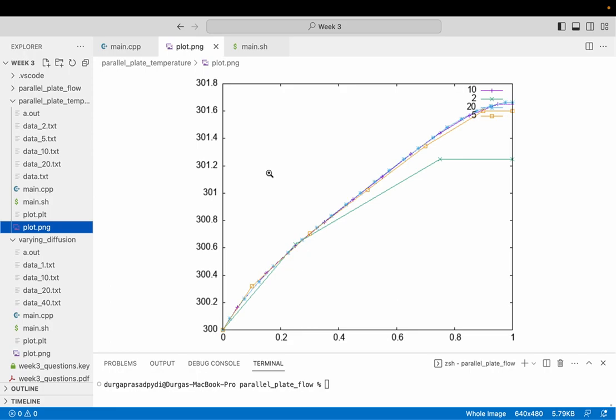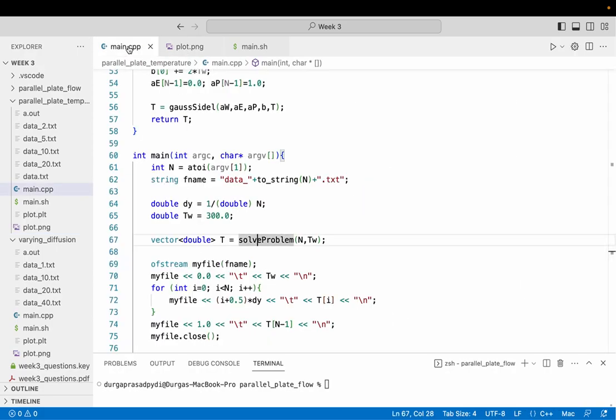Usually this term gets significant only when you have very high speed flows, that is only when you have the velocity gradients to be significantly higher. Your source term has a du dy term, del u del y. So you have this parabolic profile, so that is pretty good variation, right? Del u del y depends on your mean velocity, roughly your average velocity. This is a parabolic profile, but the rate is not so much. Exactly. Only when you consider very high flows, but the problem is if you consider high speed flows, it will be compressible and these equations are not valid. We derived it for the incompressible case.